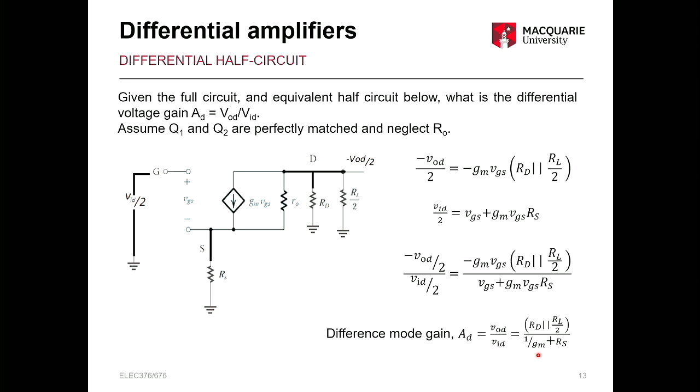Okay, so this circuit was now a little bit more complicated. We added in some resistors. We've got the RS, the RL. That changed our gain, but if we make assumptions about the size of those, we can kind of neglect them and get back to our original gain. That's always a good reality check to do, to make sure you've got the right expression if you're deriving it yourself. Okay?